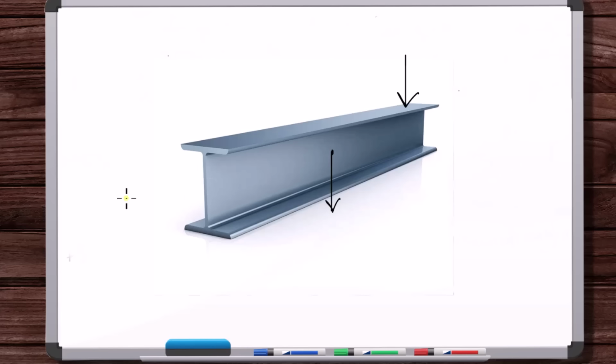Well, mechanics of materials is where you really get into this topic in detail. You're making cuts in members and analyzing the different pressure distributions and the locations of resultant loads that result from bending or twisting or axial load or shear. You really get into that in detail. But for this course and for this video, just so we can get an introduction to free body diagrams, we're going to put all of the reaction forces, the tails of the reaction forces, at the centroid of the area of the cross section that we cut.